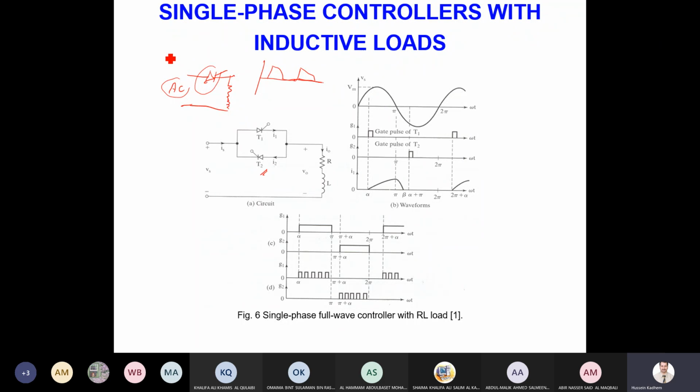Okay, you remember, but I will remind you. It's a rectifier circuit. Did we study this circuit before? Yes, great. So we call it a half wave rectifier circuit because we are only rectifying half of the wave, with one switch. We have one switch here, right? We studied this before. We just added another switch here.